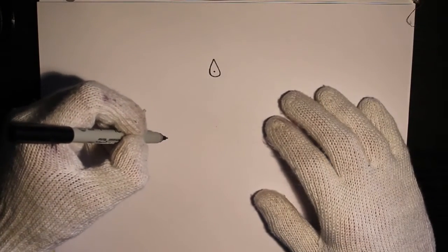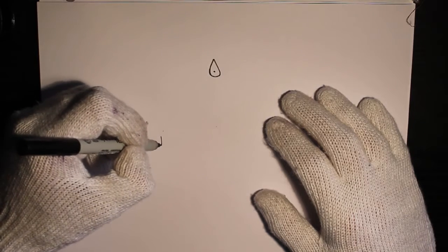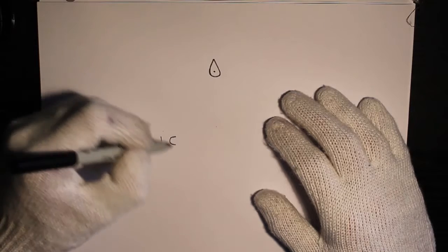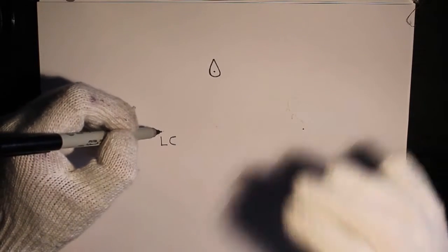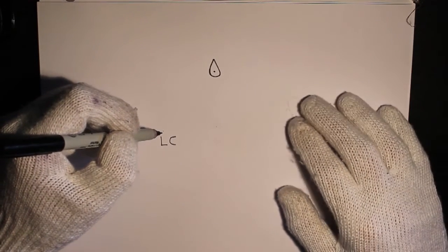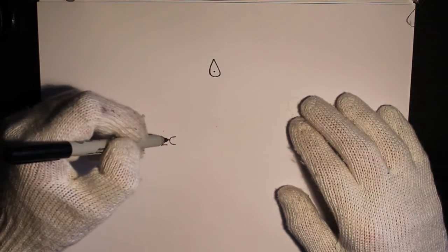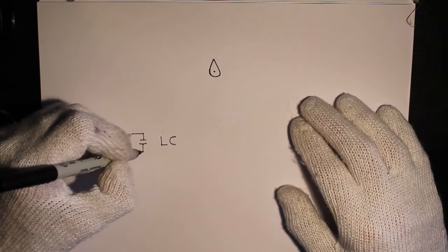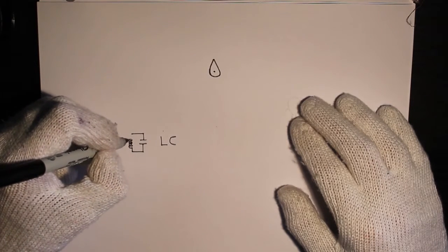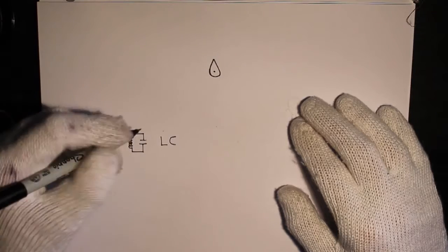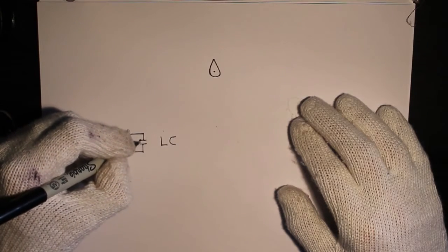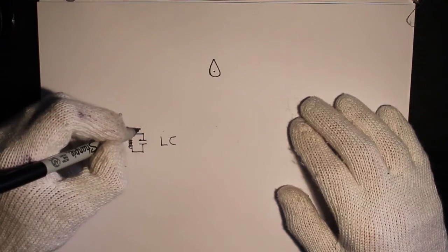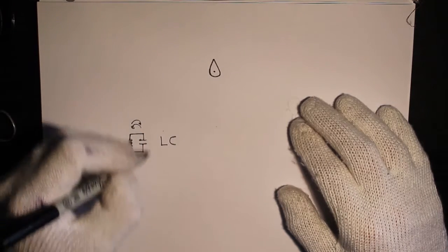So the quartz crystal is one. There's the electrical oscillator, which is literally just the rings and the coils which form an oscillator, because they're wired like one. You have your capacitor and your coils. The capacitor is formed because of the gap and the capacitance between the two rings, the alpha and omega rings, and the coils around the magnets act as an inductor so that there can be a swing backwards and forwards oscillation.